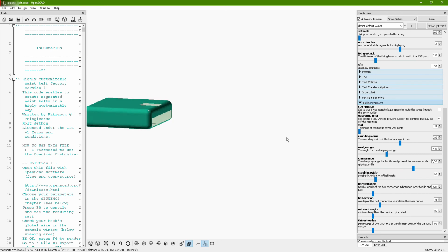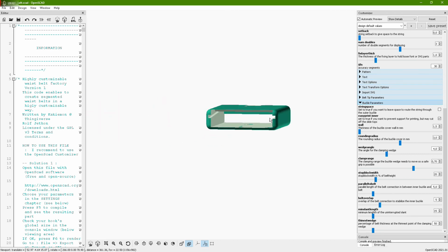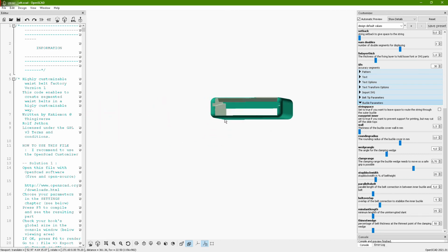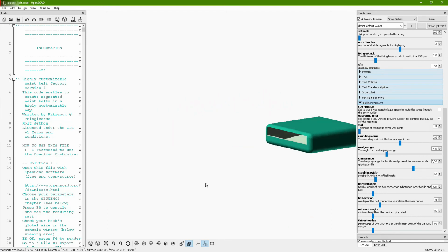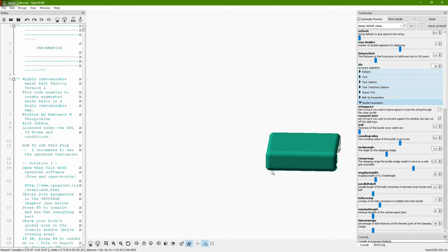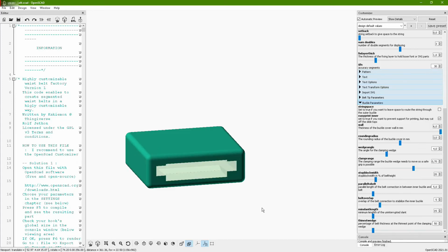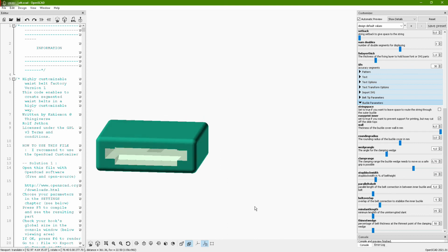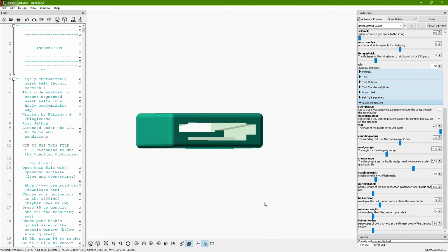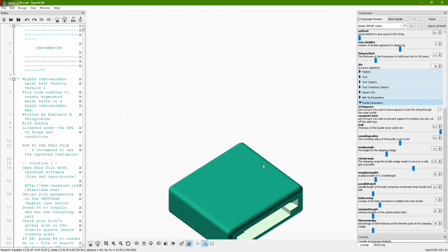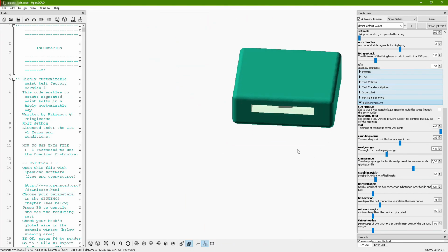Now it's very thin, you see. My guides are smaller, and also the walls of my buckle are smaller. So I can define with this one how large my buckle will become, or how thick or how stable it becomes. So I can even, if I say I want a bigger wall, let's say go for 6 millimeters, which normally doesn't make any sense. You see, you have a lot of space inside. So it's now quite stable, but it's up to you what you define.